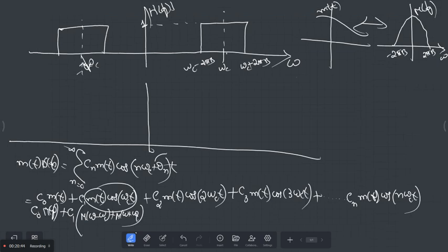Right? Now, can you tell me, how do you draw the spectrum of this M of f? As it is, I will just write this as it is, same M of f only. This is 2 pi B, this is minus 2 pi B. Plus this one. Now what is this one? Shifting, right? This is shifted by omega c, shifted by minus omega c, yes or no? So same, I will have one here shifted by omega c, and here shifted by minus omega c.